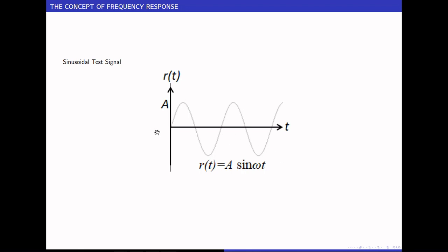But if you take any sinusoidal signal, that doesn't happen. Even when t tends to infinity, this sinusoidal signal oscillates. Its value changes from one value to another, but within some bounds. So it doesn't reach a steady state value. Therefore, you cannot apply the final value theorem. That's the problem with the sinusoidal signal.